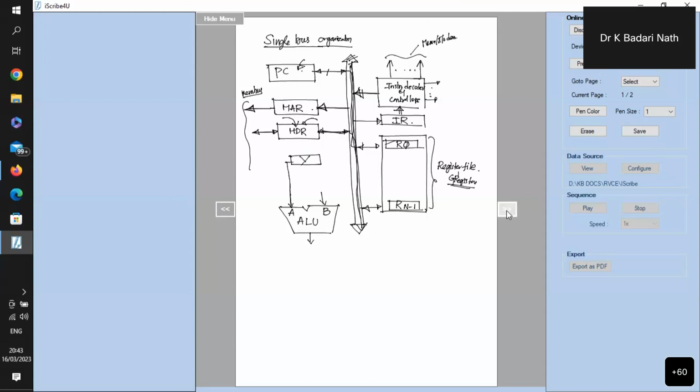So this Y register is connected to the processor. What is the purpose of this Y register? Whenever we want to perform addition of two numbers, first we bring the value from one of the registers into the Y register, which holds the data temporarily. Then we can direct another register to the bus, which is connected to the B input. So the Y temporary register is required to hold one of the two operands because there is a single bus.